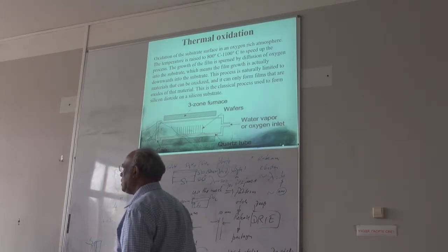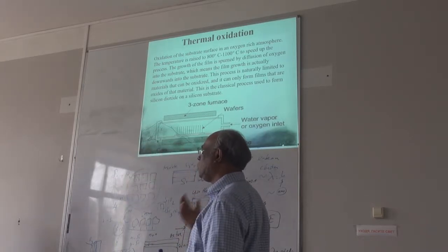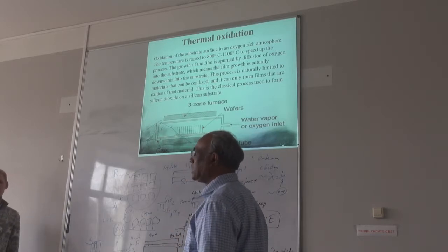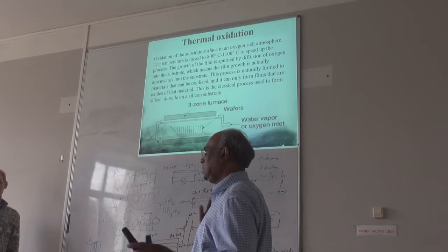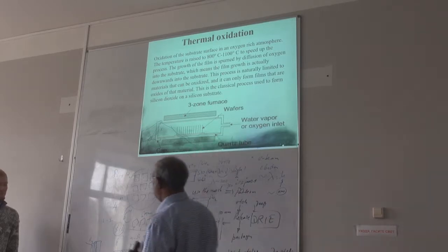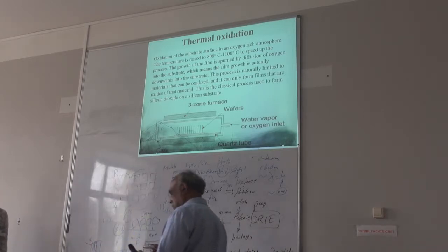Yes, because the diffusion process is happening. Some go from the middle of the wafer to the surface, and you have some silicon vacancies and oxygen vacancies. You always have that. But in the bulk there are no defects. It's mostly close to the surface that you can have some defects.